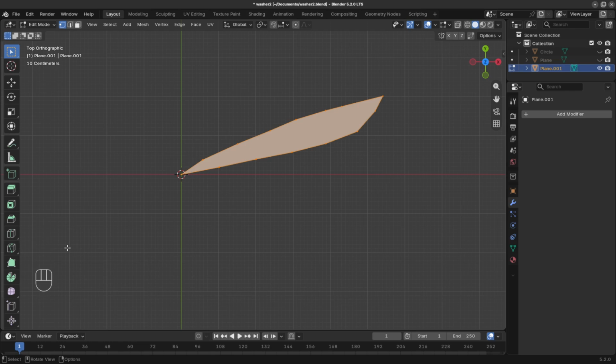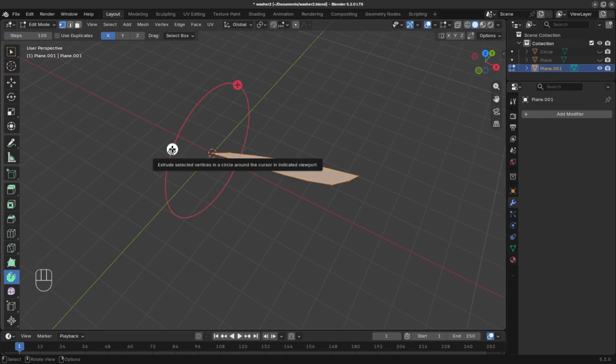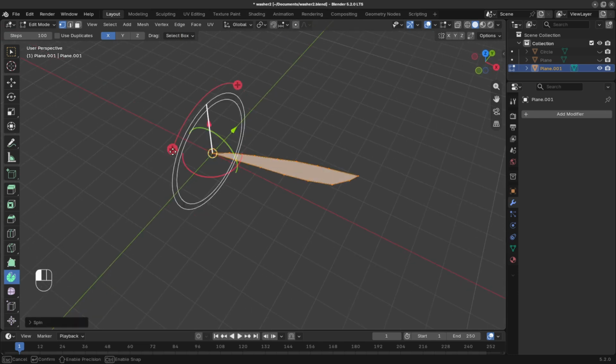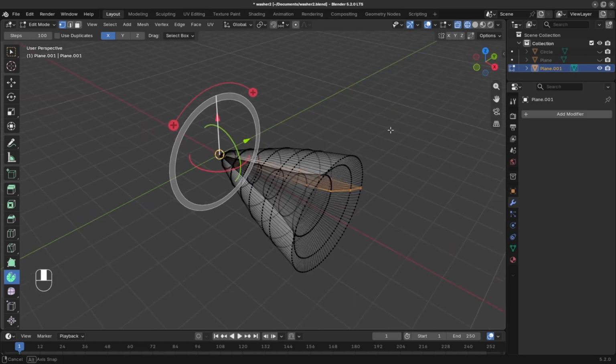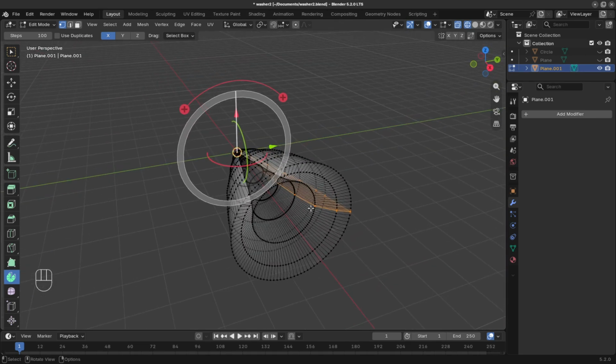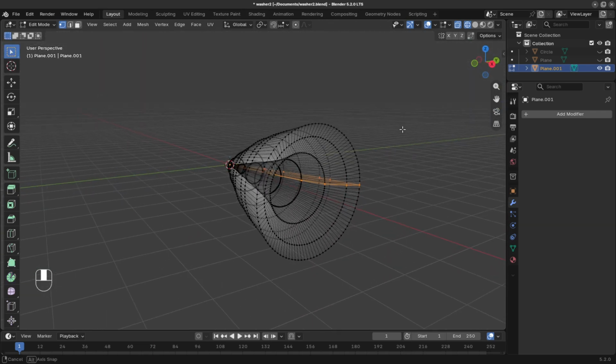And again, I'm gonna use the spin tool. So I go ahead and click on that. And same thing as last time, I can press this plus sign and that rotates around the x-axis. And I'm gonna use wire mesh view so you can see it. Okay, so there's the 2D shape that got rotated around, and that made the 3D shape of a funnel.